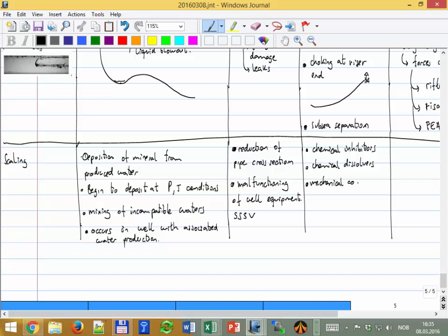Okay, when the problem is too bad, that you cannot open the valve, then you might use a small drilling bit for mechanical removal, to remove the scale, to open the cross-section area. And also it has been proposed pipe coating, okay, to avoid the deposition of scale on the pipe walls, to avoid that they will attach.